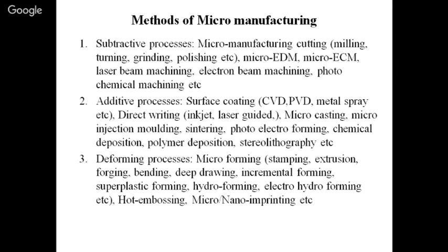Now the gap is very near, and then electrons try to jump from one element to the other, and thereby the potential difference is reduced, and pressure is applied on this particular water, and then high pressure is applied on your plates or the metal which we are interested to bend or make into the shape we desire by the forming process. So this is, you can say, a hybrid process. Hybrid means one is hydraulic as well as electrical.